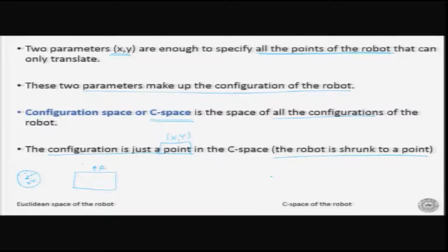So, what it basically means is what are the positions where the robot can go and sit on the obstacle. So, these are the limiting conditions. The robot can go only in these locations. It cannot go inside. Now, if I draw the position of the robot on the obstacle like this, and I take the center of the robot which is the x y, then what we will get is basically a line like this. So, there will be curves at the ends and these are going to be straight lines.